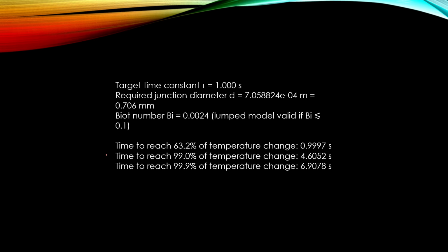And it seems that if we put this thermocouple to 200 degrees C, it reaches 63% of this temperature change in less than 1 second, and it takes around 7 seconds to reach 99.9% of this temperature change.